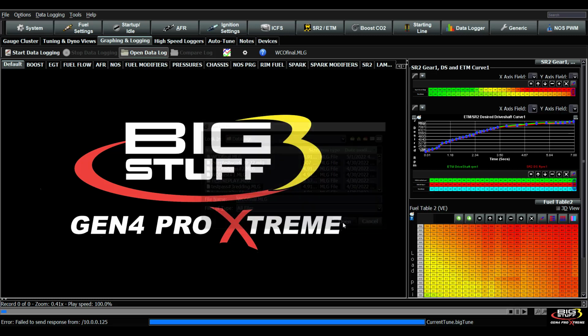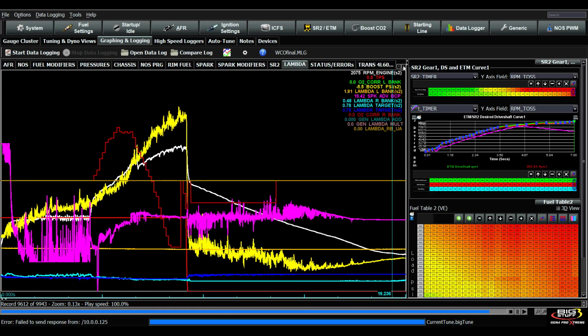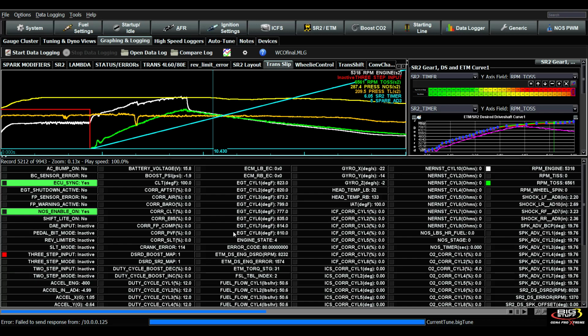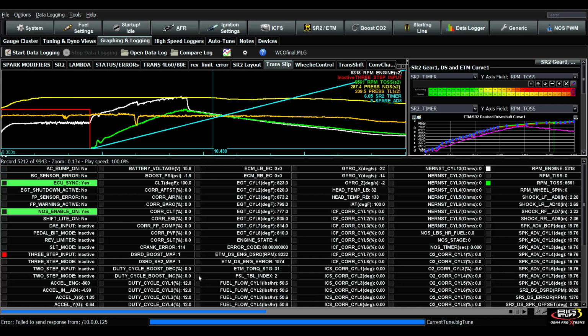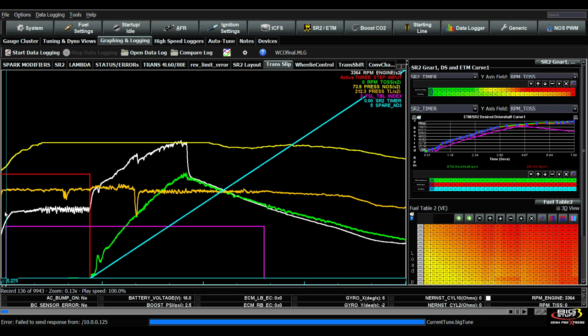And let's bring something up here. If I go into my default tab, I'll go into a tab that doesn't have that much stuff on, and it'll make it easier to see. We'll just go to Translib. So if I come over here to FSL, sorry, my computer's wigging out here, FSL table index 2, right over here, this purple line that turns on right there, that is the second set of injectors turning on based on duty cycle.